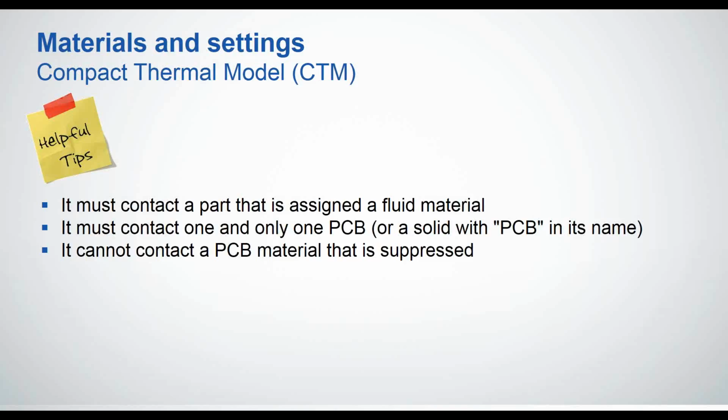And it cannot contact a PCB material that is suppressed. If you have a PCB material next to it which is suppressed, an error will be issued and the solution will not run.